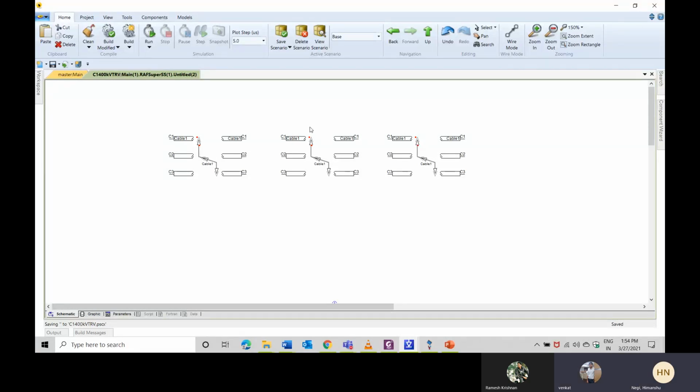So what happens is, when you are bonding between those two cables, where your cursor is, there will be an earth, and that will be jointed down using the wire. As you said, between two particular cables, all the conductors will go forward to each other, whether transposed or untransposed, but the sheath will come down and go to a link box, and that link box will have a surge arrestor on each junction. Yeah, I get your point now.